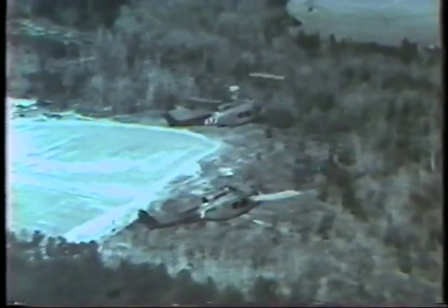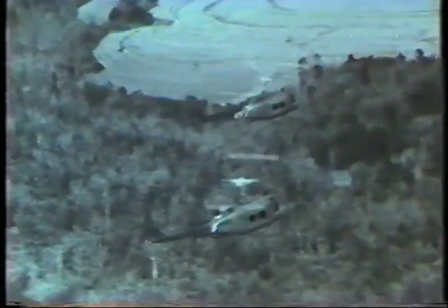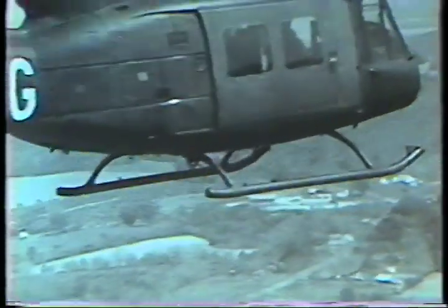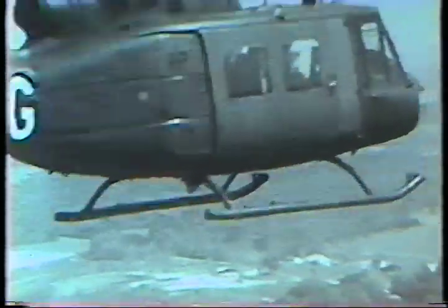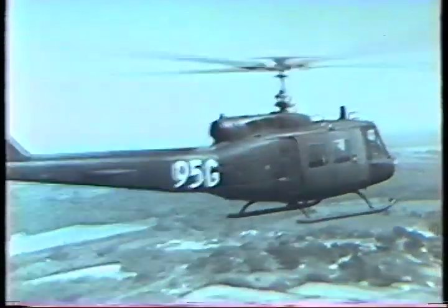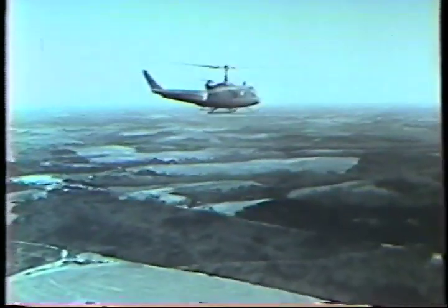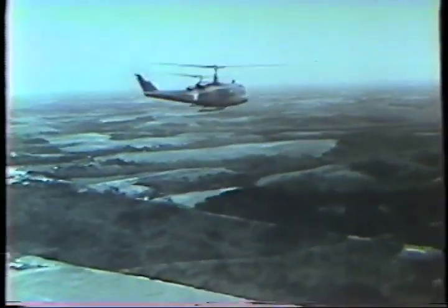Before you can fly safely in any formation, you will have to learn the techniques of maintaining your position within the flight. With the exception of the trail formation, each aircraft will always fly a 45-degree angle off the aircraft he is to maintain position on. In aligning your aircraft to another aircraft, the 45-degree angle is best obtained by positioning your aircraft so that you can visually align the far front cross tube and the nearest rear cross tube at the point where the cross tube joins the skids. As soon as the flight is formed, a 3-foot vertical step-up will be established and maintained.